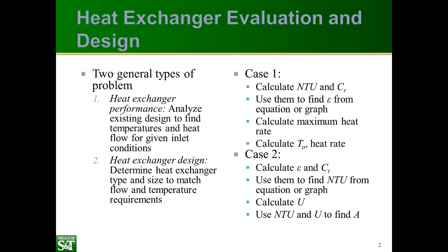And then we can use the NTU and the overall heat transfer coefficient to find the total heat transfer area we need. And that area is then going to tell us how many tubes we need or how long we need the tubes to be.